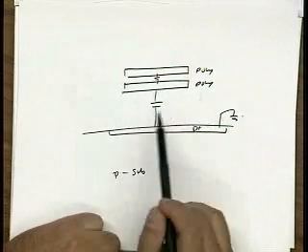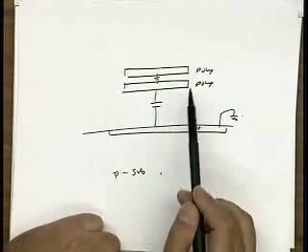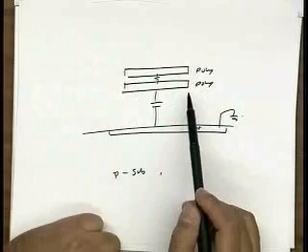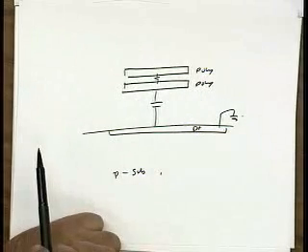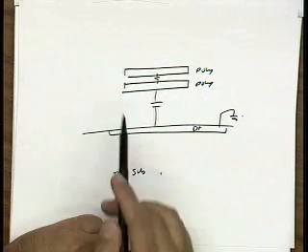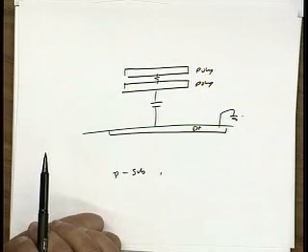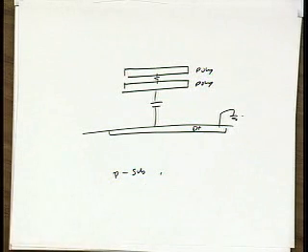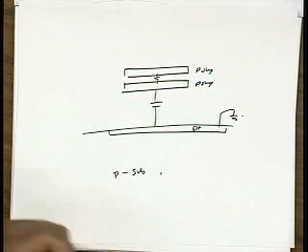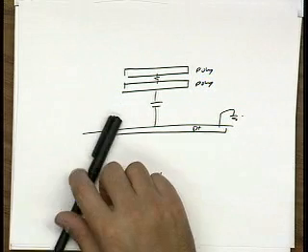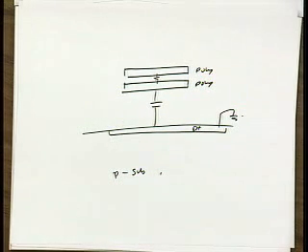So in circuits, especially circuits that depend on charge, I want to make sure I do good accounting of charge. I want to know where my charges are going. And this is a good way to capture the fringing fields and terminate them at a known point. Okay? Question? Yes. Is the poly the same as a gate poly, or just different? One of the layers is the same as the gate, and then there's a second poly layer in this particular example. Now, so the back gate capacitance is going to be very huge, right? Because it's gate. Yeah. Exactly.